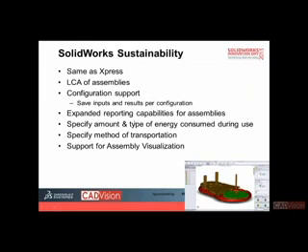And we also have the capability to do assemblies. We call it SolidWorks Sustainability, which is another add-in available on the SolidWorks platform. Everything is the same, but the extra thing is that we can do LCA of assemblies. We support configurations, which means sometimes we put different product versions in different countries in different configurations. It is very easy to change different parts, different versions, and refresh the report very effectively.